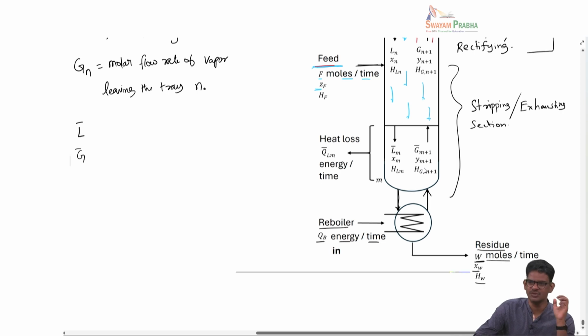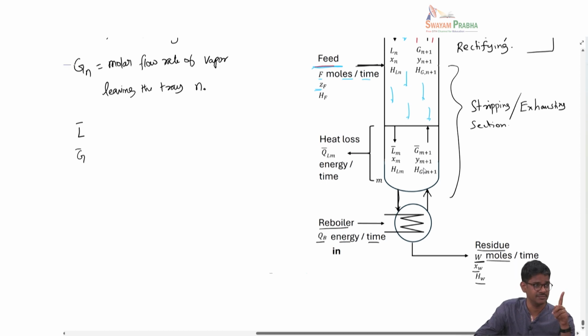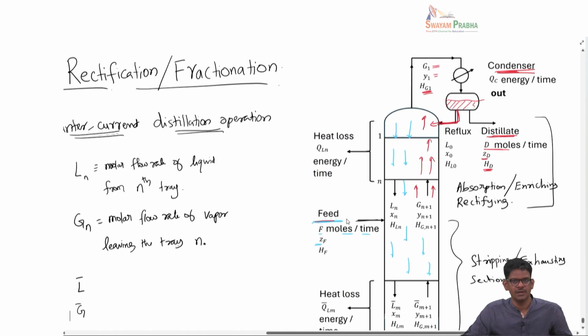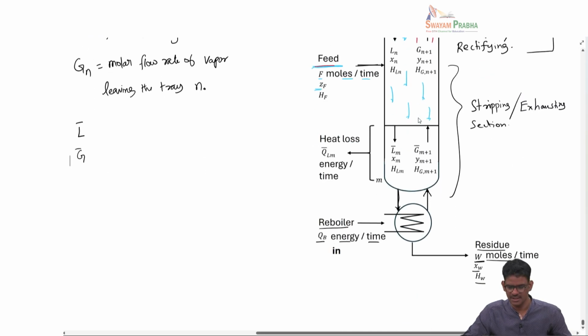Now, if you remember, the absorption that we discussed again involves a gas-liquid kind of operation. It's a single column. Gas enters at the bottom, leaves at the top, liquid comes in at the top and leaves at the bottom. The liquid and gas flow rates are pretty much fixed, almost constant throughout the column. So you have one operating line, and from that one operating line we have the staircase construction to find the number of stages. Here, the reason I'm saying this is that, having fixed all the flow rates, if you look at the top of the column, the liquid and gas flow rates would be of some extent, and if you come to the bottom of the column, you would have different gas and liquid flow rates.